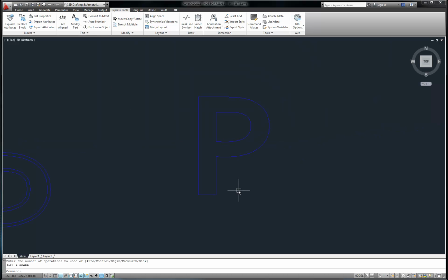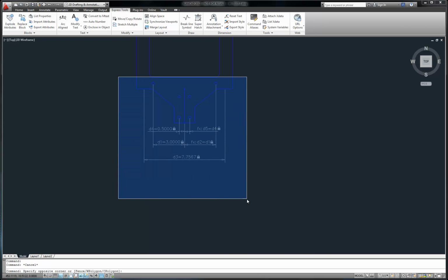This is the issue with font. Font is not a standard entity. It's got just a gazillion little pieces to it. You can see all these are small pieces of a font, and there's no way that Inventor is going to be able to handle this. So here's what we're going to do. I've done that. Then I created our little piece down here, and I'm just going to copy this right now.